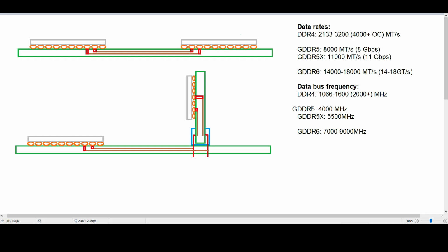So really what we want to do with a signal line like this is, especially when we're operating at these very high frequencies that we have in GDDR, which are, what, 6 times maybe higher than what we're using in DDR4. So suddenly we're much more sensitive. We have to change the voltage much more quickly. So it's much easier to have these reflections damage the data that's being transferred.